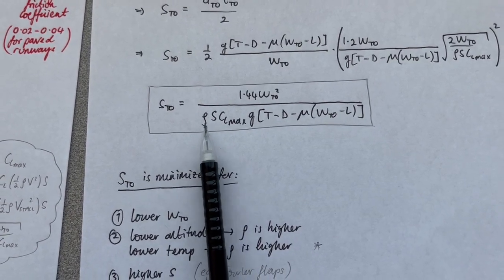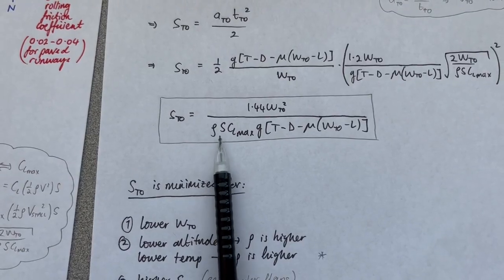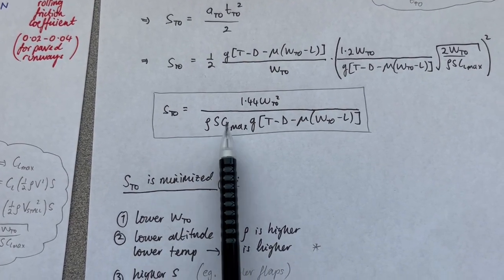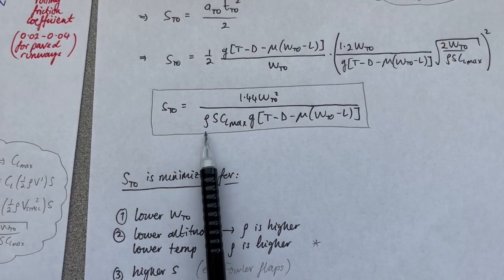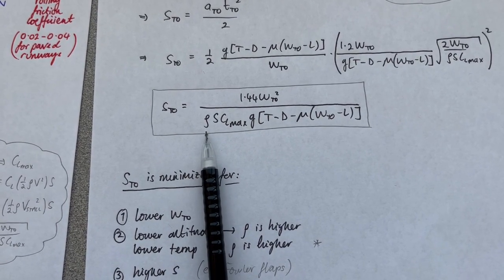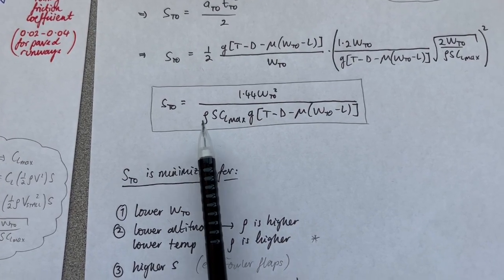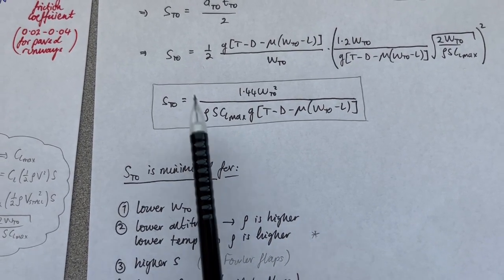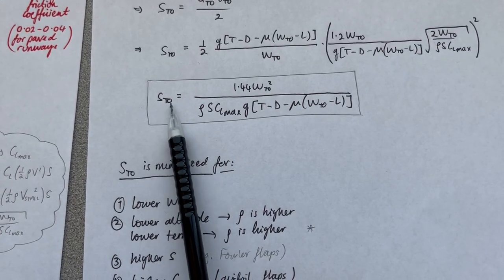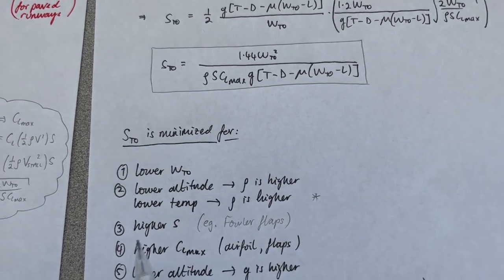If the temperature gets so high that the air density reduces significantly, that's going to extend our takeoff distance, isn't it? So that's why certain airplanes, think about big commercial airliners, for example, like 777s, A380s, big heavy airplanes, if the temperature gets too hot, then the takeoff distance actually can get too long for the runway in question. So that's how that all kind of lines up.